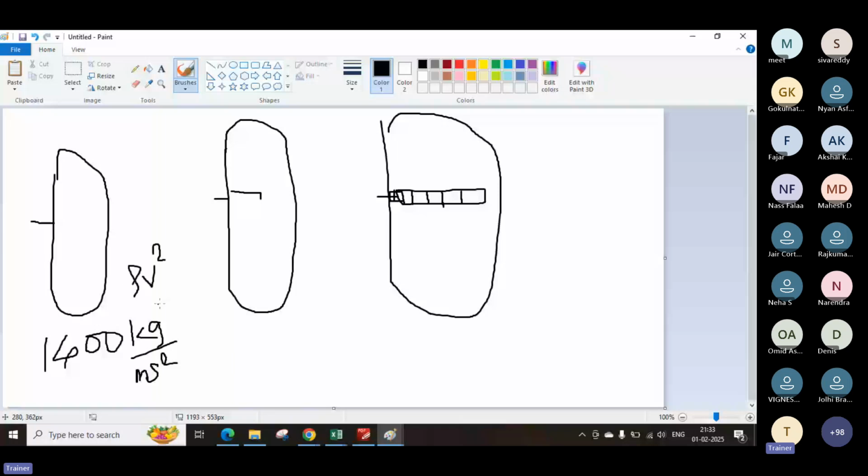So you know this velocity, how to calculate. You know the size, the assumed size of this nozzle. So you can calculate the Q by A, that is the rho v square value. This V is the velocity. However, this rho is the rho of a mixture. It's not the density of a gas or density of liquid. It's the combined density of this inlet or incoming feed.